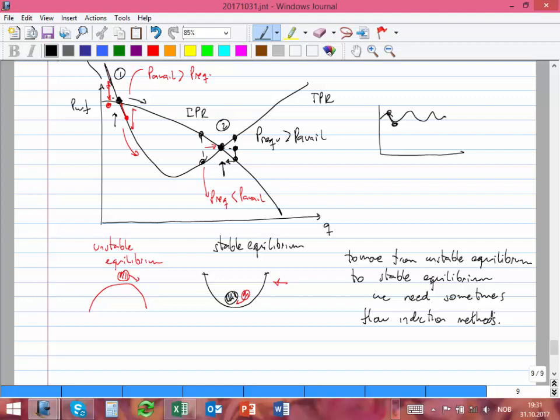And there are all kinds of methods, but basically I try to help the well somehow to increase the rate, push it past the first equilibrium point such that it will go to the second. And that's where I want to produce.